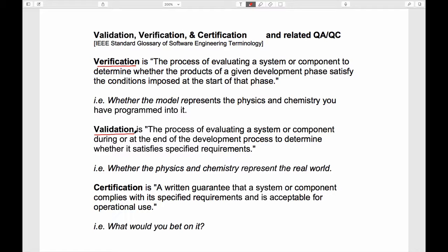And so you could get a solution for the coupled solid mechanics flow process we just talked about, loading an aquifer, that perfectly adequately addressed all of the physics that you have in your problem. But if, for instance, in your model, a big part of that compaction, say in late time, was just due to chemical dissolution at stress contacts within grains, pressure solution, and that it kept on deforming after that, if you didn't have that physics in it, then it wouldn't give you the solution that you'd see in reality if you instrumented a site that was doing it.